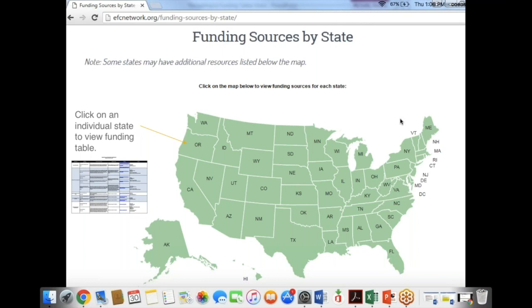And so basically just by bringing in other considerations into the story instead of just age, you will find out that the useful lives are quite different than just saying, well, my pump is 10 years old and pumps last 10 years, so it's 0. Well, your pump might last 20 years. It might last 5. I mean, it's very different than just an age-related question.